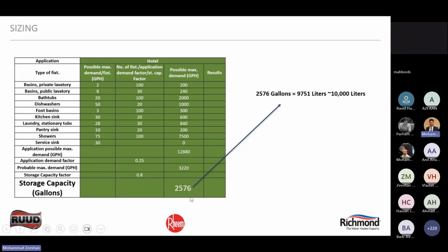You need to multiply these with the total, which will give you the total demand. Now, mind you, these codes are all designed keeping boiler systems in mind. The key difference between boilers and heat pumps is that they don't work in a similar way. The heating is completely different. A boiler system works on a quick recovery basis, and all our codes are based on that. Heat pumps have a slower recovery, slightly double that of boilers.